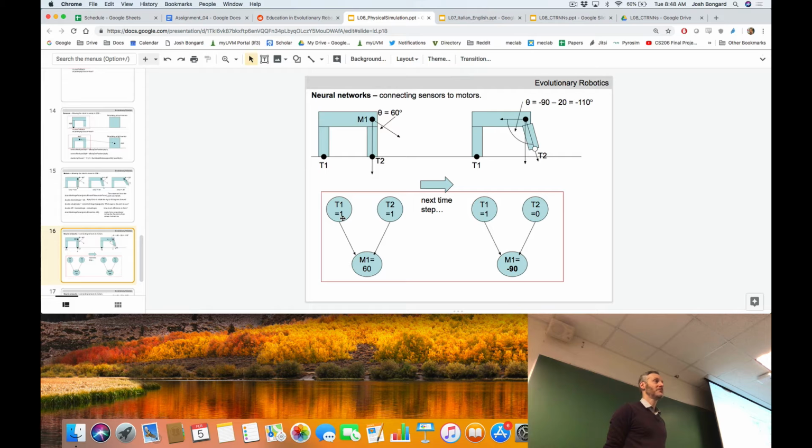If you include more time steps in a simulation, do your chances of it overshooting the desired angle decrease, because it's able to lower the acceleration over time? That's a good question. Not if we add more time steps, but if we reduce dt or delta t, the amount of time between one time step and the next, which we talked about last time, it makes it more accurate, which means you're probably going to get less overshoot. Remember that as we make dt smaller, we generally get less change in motion between one time step and the next. So it's likely going to be a much smoother transition towards the desired angle, which again you can play around with in your code.